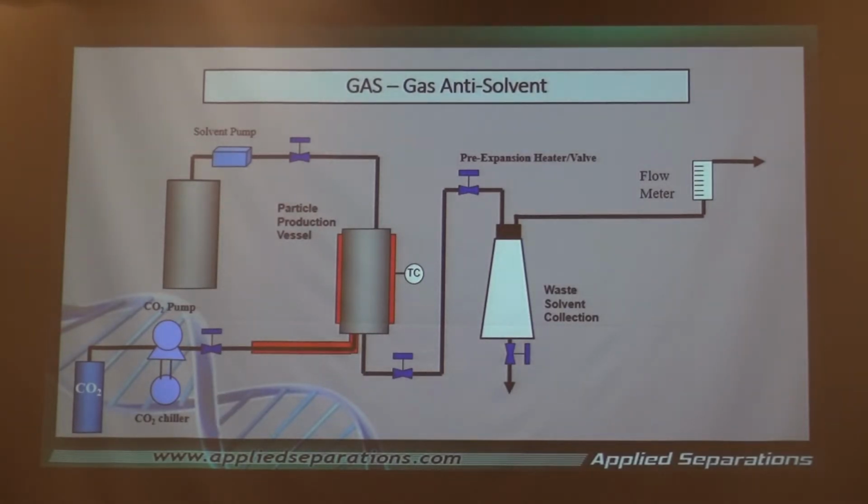And then let me show you this way, instead of carrying it through. Here's what we do first. Here's our solvent and solute. Remember, our solute is not soluble in CO2 this time. So we have it in solution here. How are we going to make particles? Now, what we wind up doing is we pump it in, a small amount. Then we bring in the CO2.